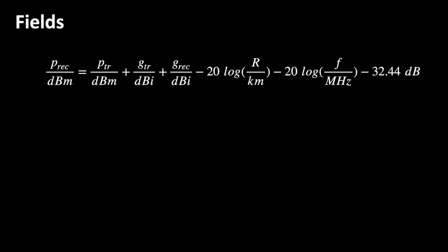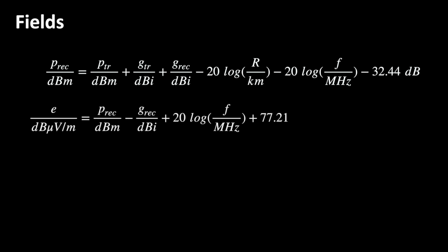The received power became so established that communications engineers are often talking about field strength, just specifying the dBm value of the received signal. This is confusing because the dBm value indicates a power in milliwatt, but not the field strength in volt per meter, and perhaps this is a reason for some misconceptions. Another reason might be that it is hardly possible to measure the electric field directly at high frequencies. You have to do it indirectly via the received power.